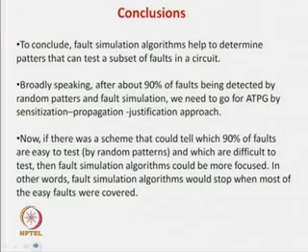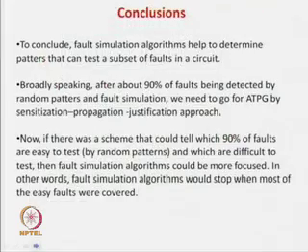But in case of concurrent fault simulation, what do we do? We compute some bubbles for all the gates. The bubbles for the gates have some values, and if there is a signal difference with the gate, we keep that faulty gate in the bubble list, and we retain all the gates at all the levels, even if it detects a fault, even if it does not detect a fault.